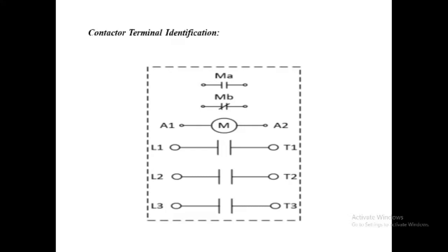In a magnetic motor starter, there are two circuits, the power circuit and the control circuit. The power circuit is the circuit providing the current to the motor. The control circuit is the wiring that interfaces the pilot devices or sensors to the control element. Separating this circuit allows you to use low voltage wiring for the control circuit regardless of the motor voltage.